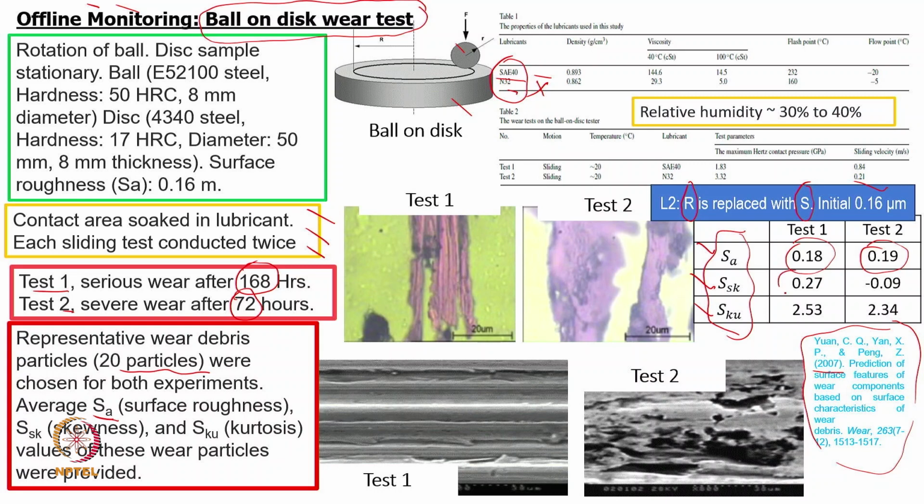Now in the previous lecture, or lecture 2 also, I mentioned that skewness will be negative for the better lubricant. So if this comes positive, here it is negative. So this is again not really giving results completely. Again, I mentioned that high kurtosis will be preferable.